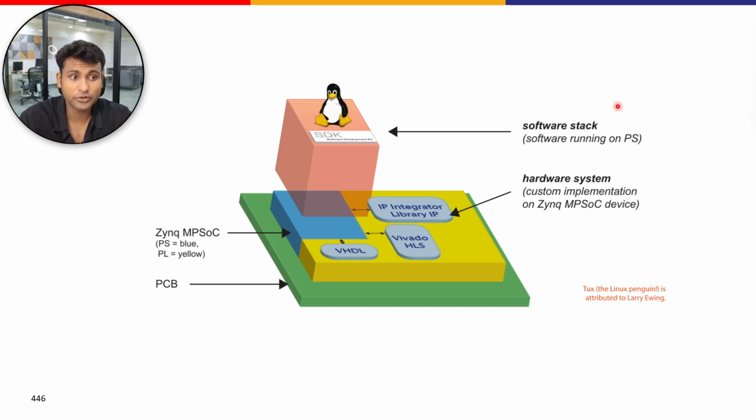The PL in particular provides a blank canvas, offering the freedom to implement any design. The designers create their own custom hardware using the Xilinx design platforms and sometimes also using third-party design tools. The custom hardware includes the hardware resources particularly taken from the PS, any IP cores or other functionalities to be implemented into the PL. It takes some IO connections, it makes use of memory, the clocks and interrupt configurations, and interfacing between all these elements.